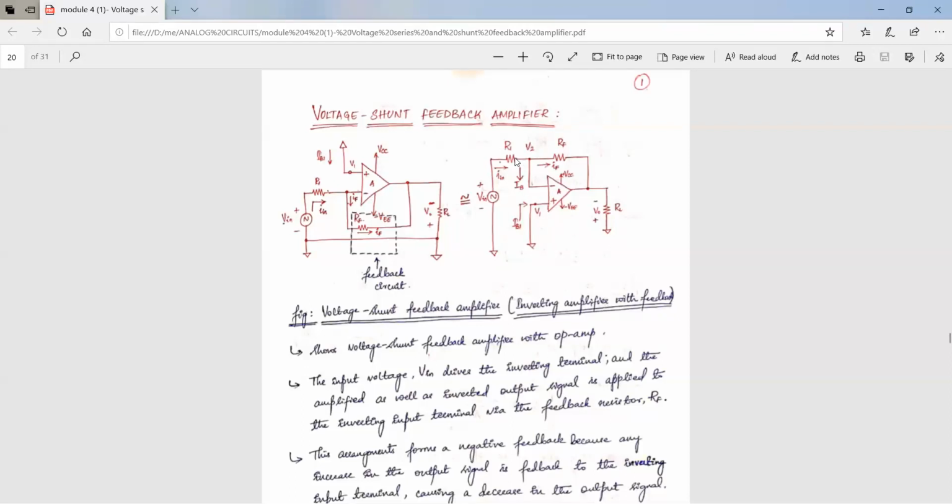through the resistance R1. And observe here, at this particular node V2, the current branches. The incoming current, the current flowing through R1, is I in, and this will branch out as IB, that is the input current to the base, and the current IF, that is the current through the feedback resistance.